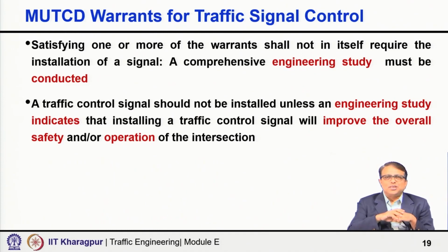It is not that when one or more warrants are satisfied, that means yes, install a signal. It may not be true. You require a comprehensive engineering study to make a conclusion.